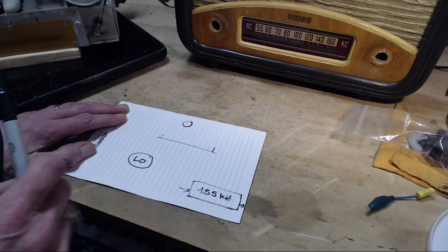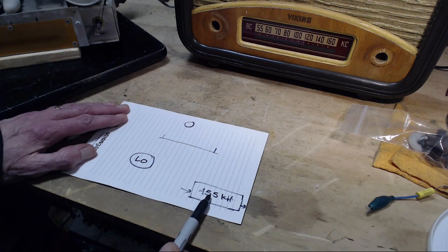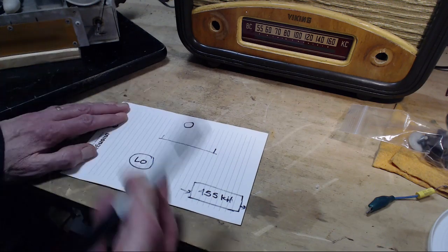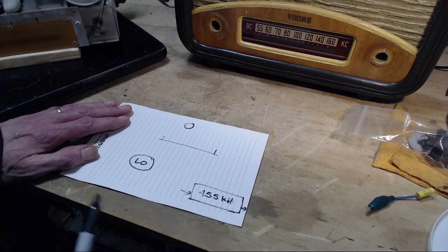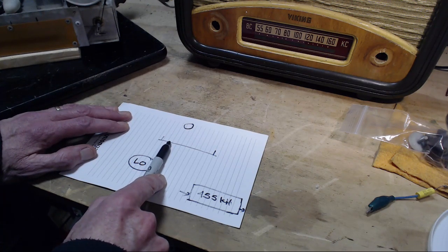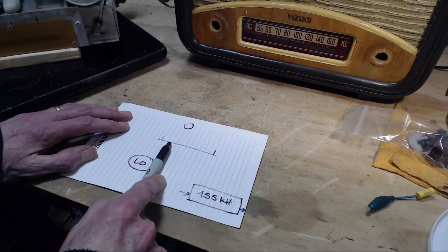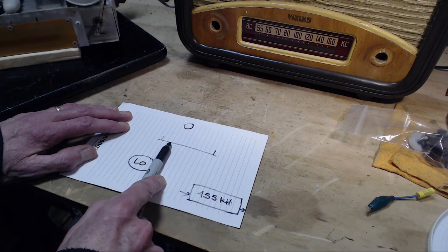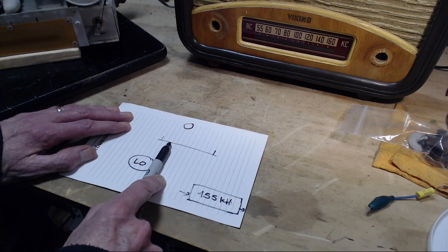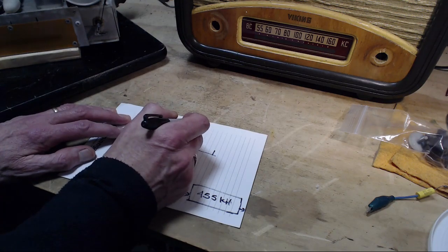So you don't really move it or change it. You create another one. You create another signal at this frequency with exactly the same information in it, the same music, the same voices or whatever. And you discard the original one. The original signal, let's say at 640 kilohertz, that's a signal I often listen to here, gets partway into the radio and then it's just tossed aside. It's done. Because a new signal is carrying on that matches it, and that's this 455 one. This takes place in this mixer tube.